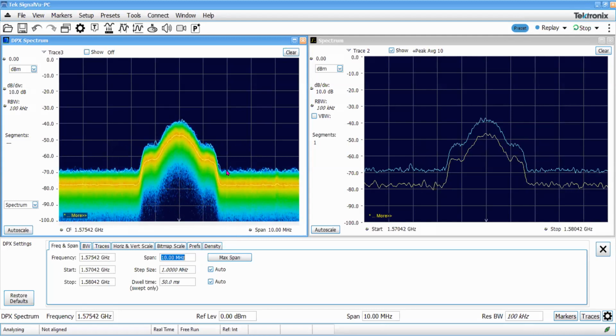Today the receivers are not only for L1 C/A; they have the capability to receive many other signals as well that have different signal structures. Some have a 2 megahertz bandwidth, some 4 megahertz, and some Galileo signals have 20 megahertz of bandwidth, very large bandwidth signals, because of the wideband modulation.